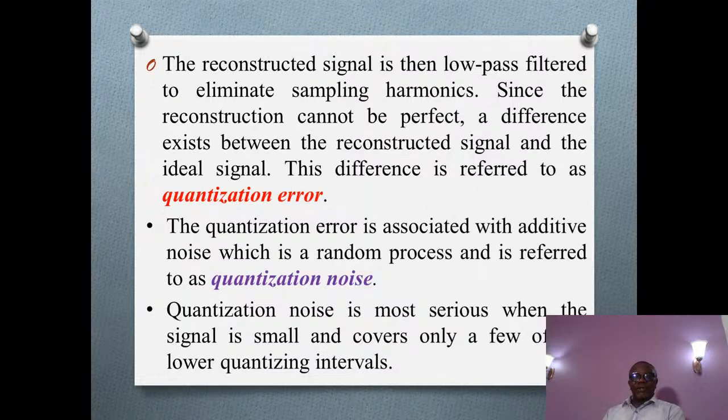This quantization noise is most serious when the signal is small and covers only a few of the lower quantizing intervals. For instance, when you are talking, the signal your voice is producing does not have a very wide difference between the peak and the lowest portion of it.